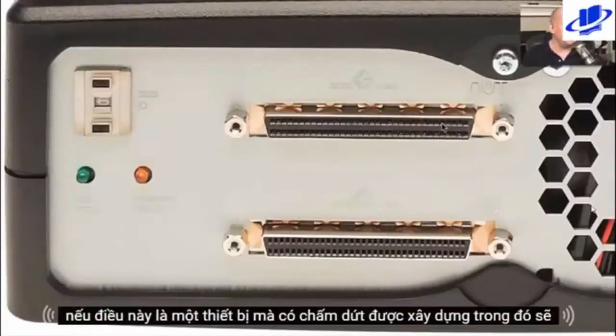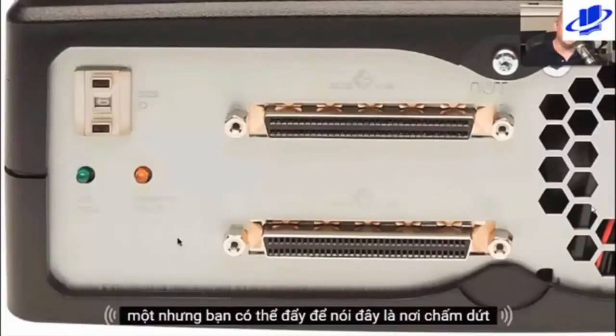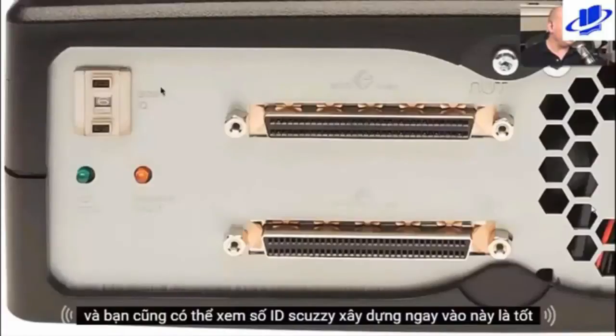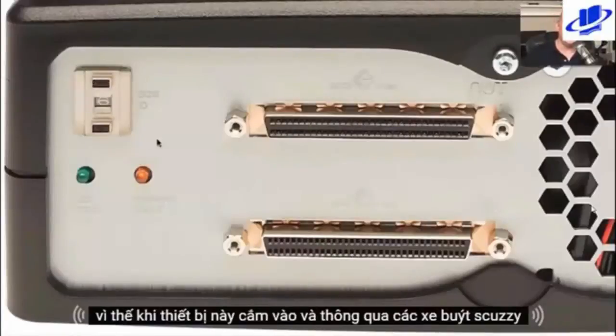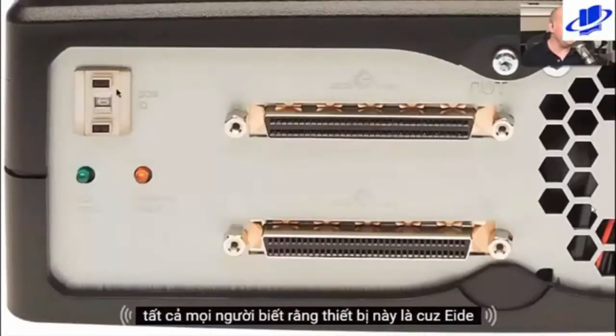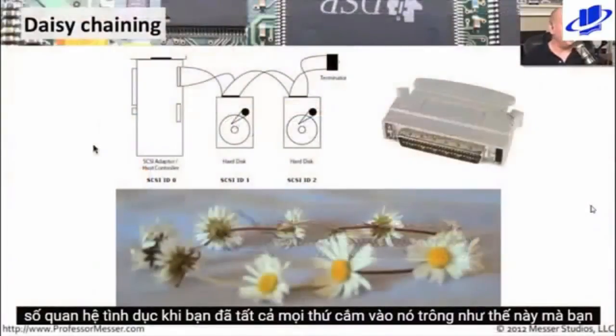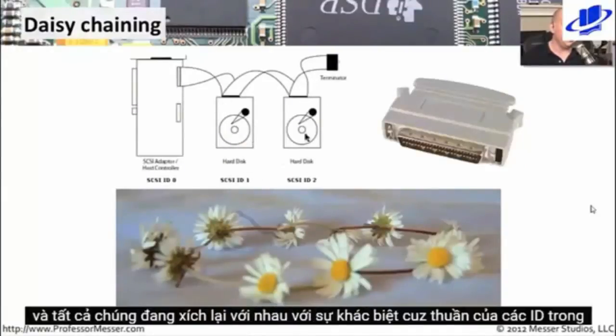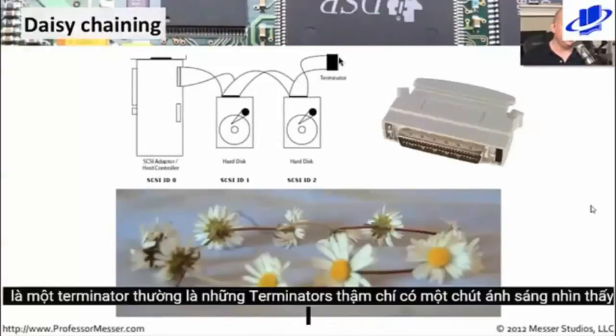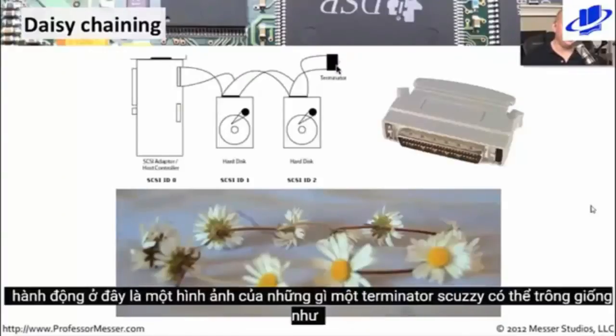If this was a device that had the termination built in, there would probably be a connector on this device, or a button you could push to say this was the terminating place. And you can also see the SCSI ID number built right into this as well. There's little buttons that would allow you to change that SCSI ID. So when this device plugged in and communicated across the SCSI bus, everyone knew that this device was SCSI ID number 6. Once you have everything plugged in, it looks a little like this, where you have a SCSI controller that might be ID 0. Here's SCSI ID 1, that's a hard disk. Here's another hard disk, and they're all chained together with different SCSI IDs, and at the end of the chain is a terminator. Usually these terminators even have a little light so you can see that they are active.